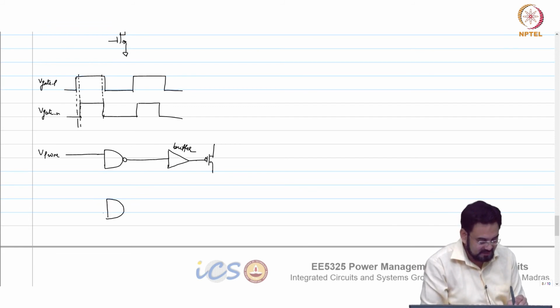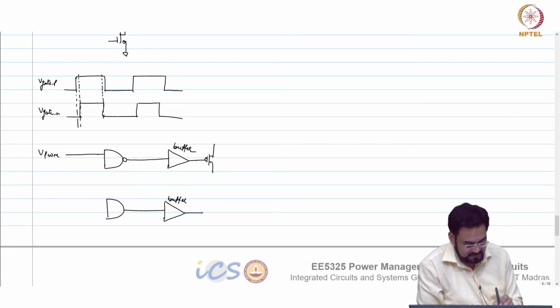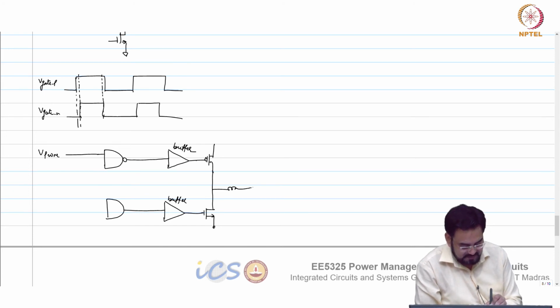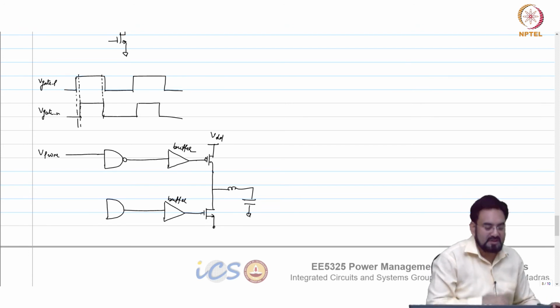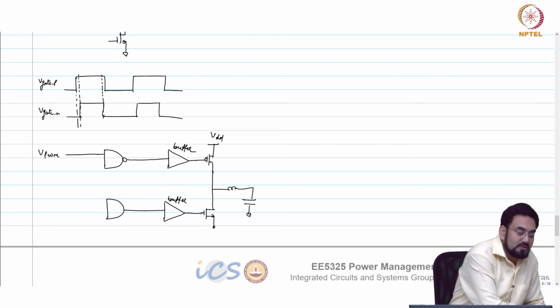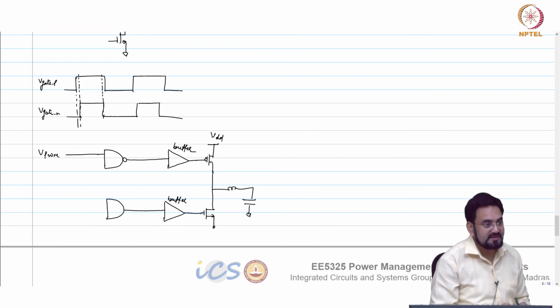And then on the other side, this is your, again, buffer. You have NMOS and they are connected together. This is where you connect your LC. And we want the gate of this NMOS to go to 0 when VPWM is high. So when it is high, I want to make it 0, okay, forcefully 0.